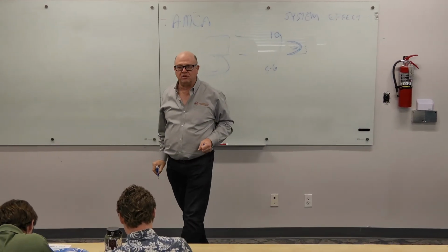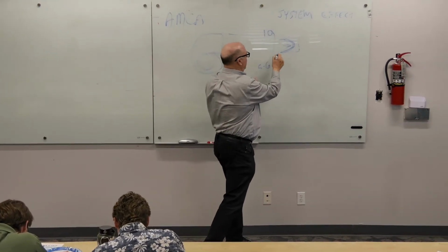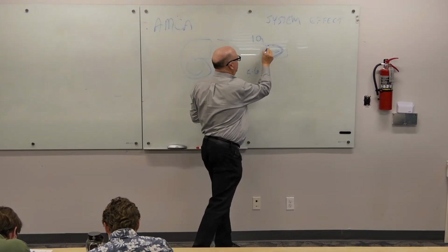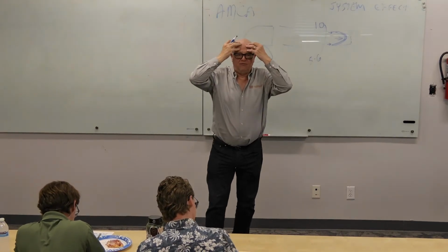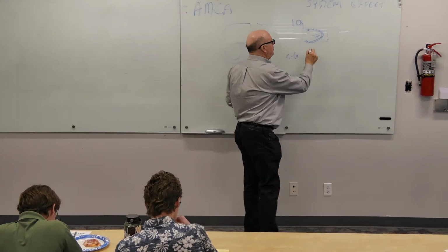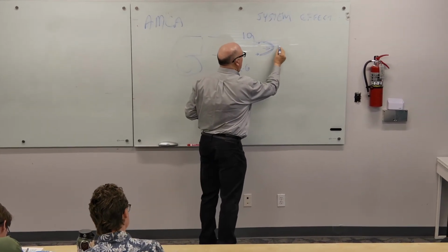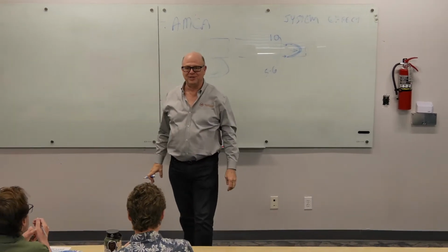Now the reason I drew it that way is because here in the middle is where the air is going the fastest, the biggest velocity, because there's less friction. Right along the edges, it's going at a lesser velocity. Now if you thought about that a little further, you'd realize that what that meant is you've got more air coming through the middle third than you do on the outside thirds, don't you?